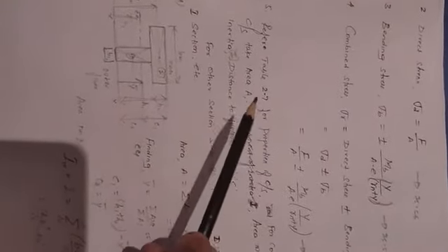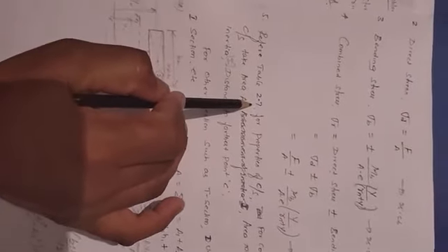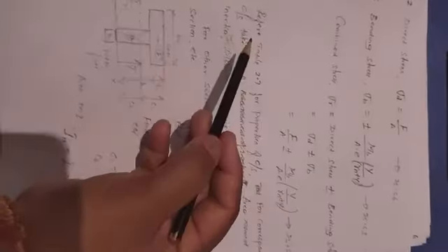Now what are some of the properties? Here you consider only a rectangular cross section, but curved beams may be a rectangle, circle, square, T section, I section, etc. A triangular section also. Then you can extract some of the cross sectional properties. Now you will refer to table 2.7 from volume 1, the property cross section table. From this corresponding cross section, take area, area moment of inertia I, and distance from the central axis to the outer fiber, C1 and C2.